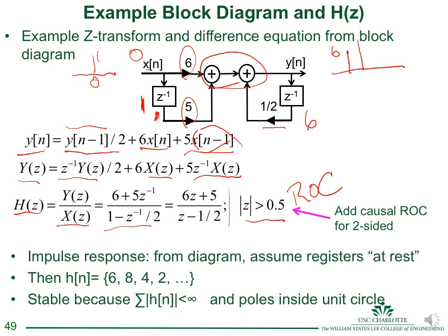At the next clock cycle, the 0 that was coming in becomes stored in the register. So the register output becomes 0. The 8 that was at the output now is stored in the register, and I have an 8 at the output of the register. And so the front part of the circuit now adds to 0, and the only thing I have left is the 8 divided by 2, so my next output is going to be a 4.